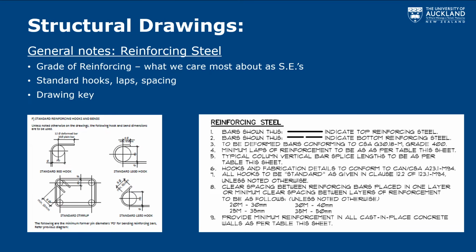Also important are some typical details. We don't want to have to be drawing these every time we draw a section or a detail on the design drawings, and so we want to make sure we hook our reinforcement so that it's anchored and doesn't pull out. But those hooks are standard, and so we just want to have those in one place at the beginning of the drawing.